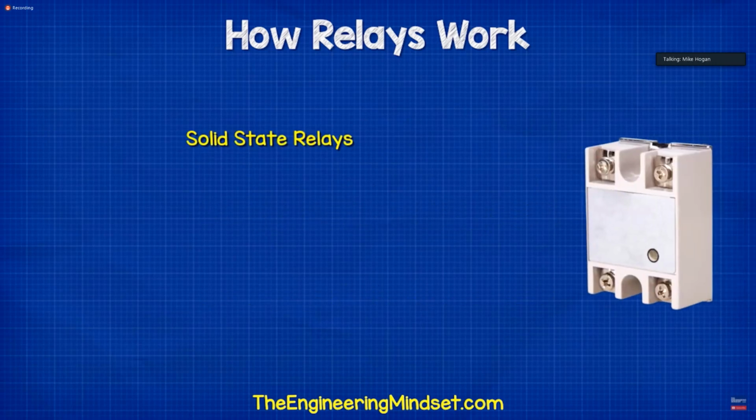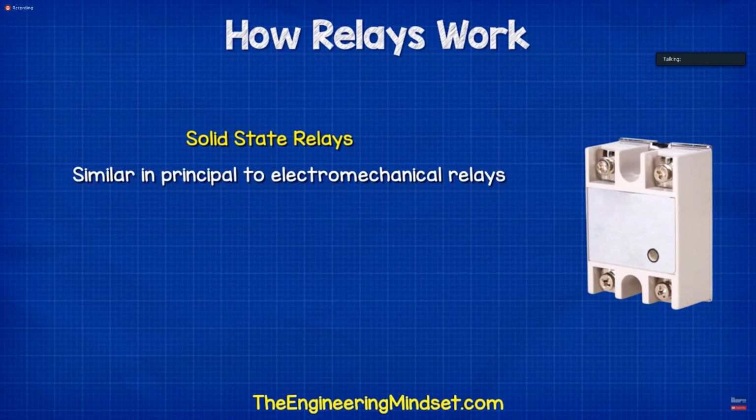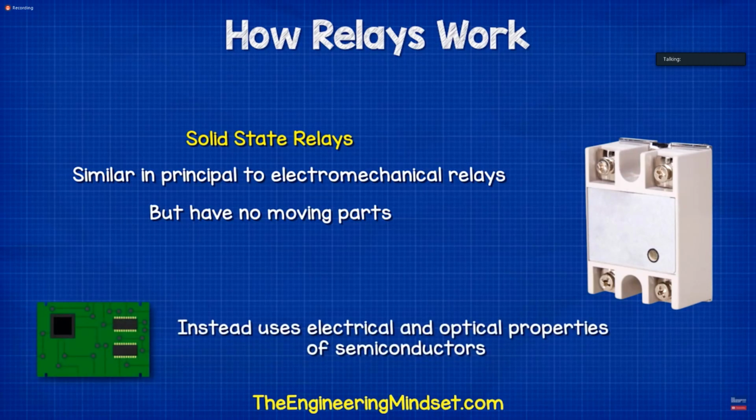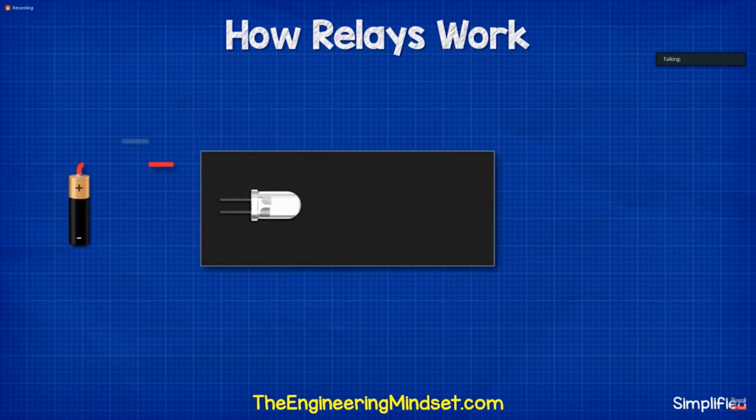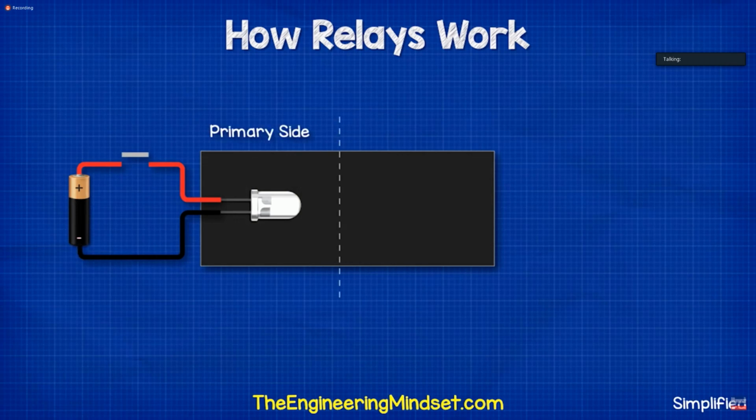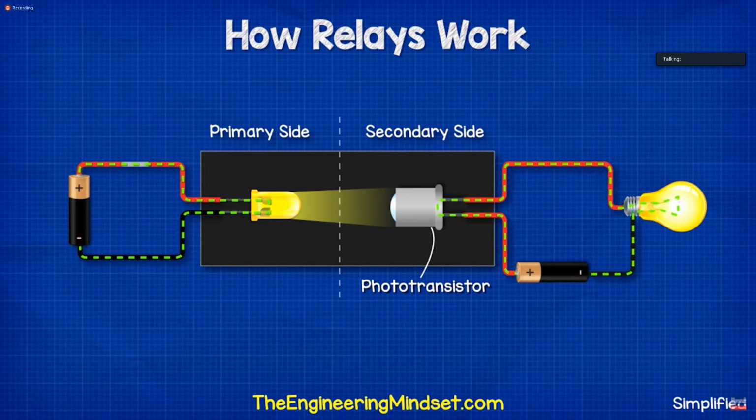The operation of solid-state relays, or SSRs, is similar in principle, but unlike electromechanical relays, it has no moving parts. The solid-state relay uses the electrical and optical properties of solid-state semiconductors to perform its input and output isolation as well as switching functions. With this type of device, we find an LED light on the primary side instead of an electromagnet. The LED provides optical coupling by shining a beam of light across a gap and into the receiver of an adjacent photosensitive transistor.